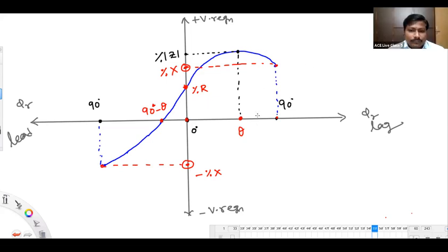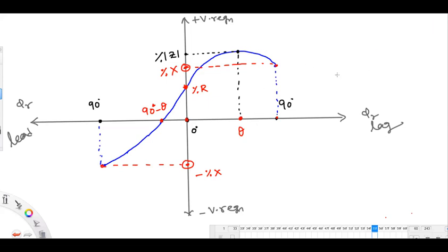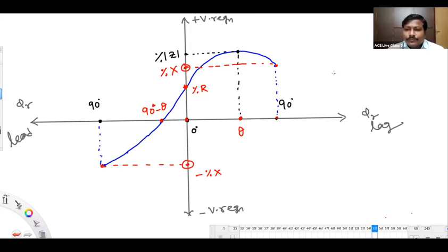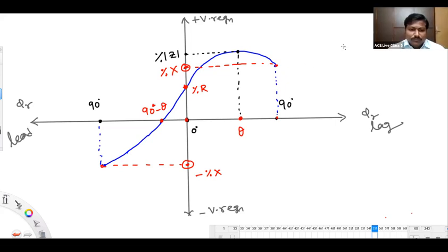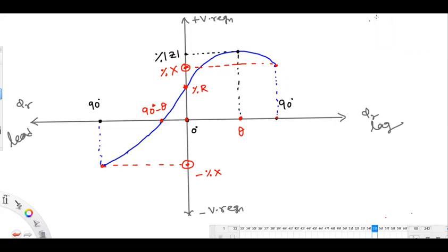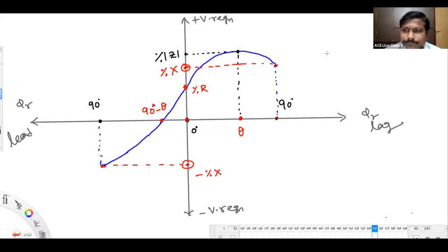Naveen Sai: Sir, my doubt is from the first chapter. You explained the selection of conductor: for less than 220 kV, it is based on current rating; for greater than 220 kV, it is based on corona. But in the material, there is a question where it is given 220 kV and the answer is corona. No, it's not corona. You modify it. Okay, sir.